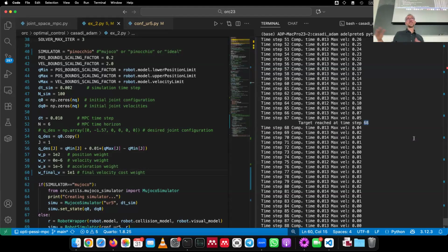And of course, there are other sets which are bigger that are control invariant, but those are not trivial to compute. So we will need to do some pre-computation, as I described. We will need an algorithm for computing an estimate of such a control invariant set. And then we could use this estimate, typically represented with a neural network or some function approximation method, as a terminal constraint inside the MPC problem, but that's much more advanced.